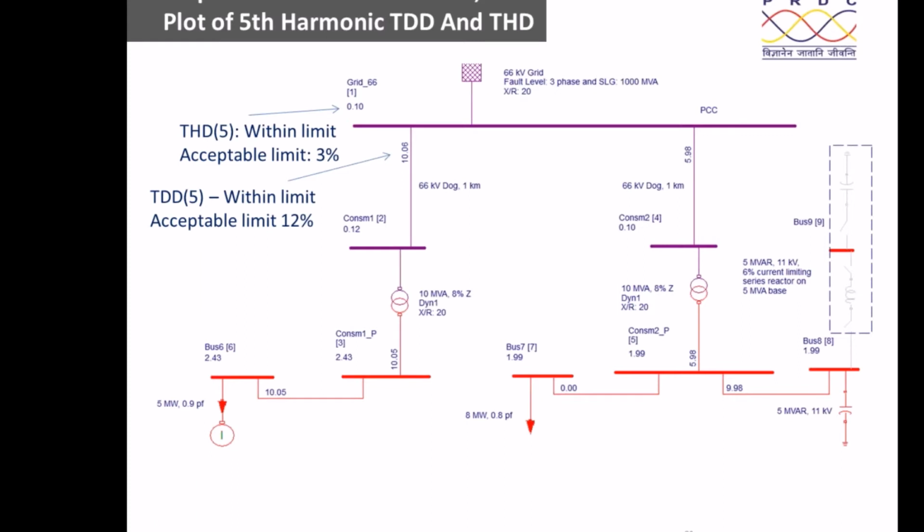For example, the fourth order harmonic is non-characteristic, because normally whenever you are using power electronic equipment like the 6 pulse converter, the predominant harmonic current is the 5th, and normally for a perfectly symmetrical current waveform, we will not have any even order harmonics. You do the Fourier transform, DFT, on the symmetrical waveform, you will find that the even order harmonics will not be there. Therefore, he should have designed a current limiting reactor.